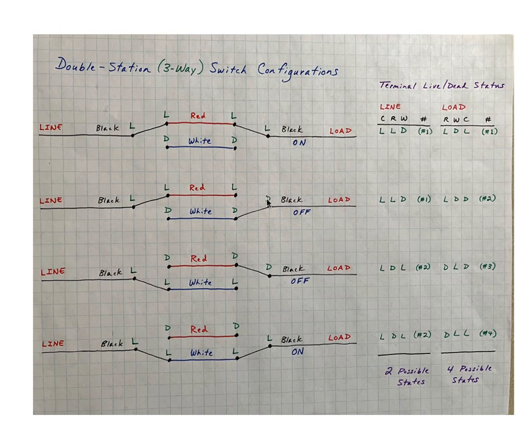And here you can study this on your own, but you see you have the off condition here, and you see why. See, current comes in, but it stops. And here you have another off condition. The current comes in, goes this way, but there's no connection here. So the load is not energized. And here's another one with the switch in the down position. Current will go on your white traveler conductor and pass on to your load. You can study this on your own.